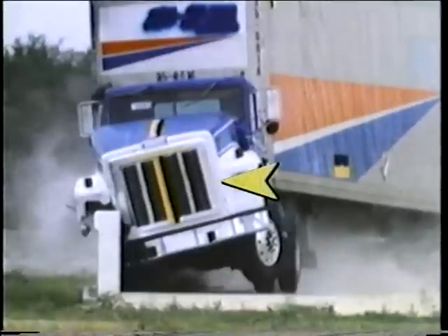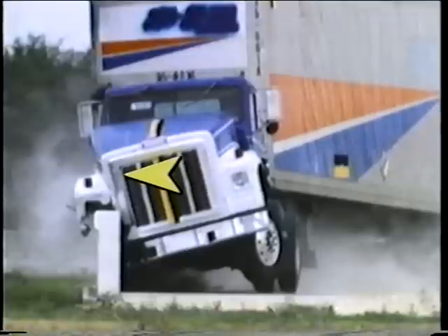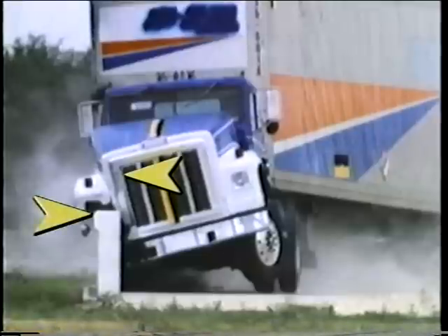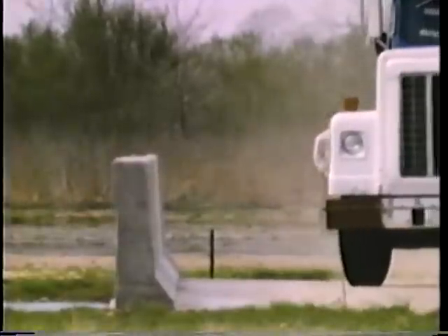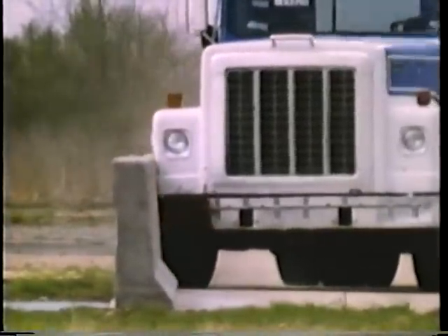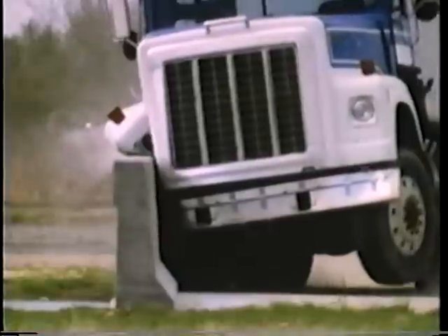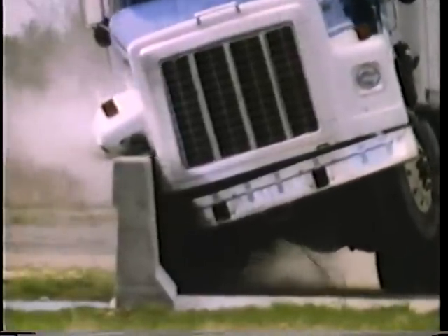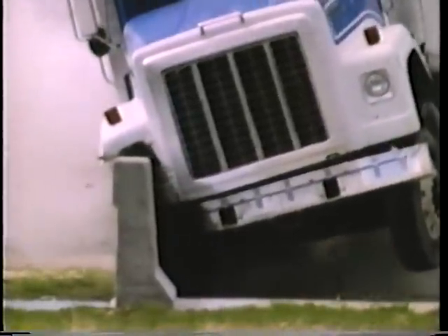If a bridge rail is too low, the truck will simply roll over on top of the barrier. When there's a good possibility that heavy trucks will strike a bridge rail, crash test experience has shown that the bridge rail should be at least 42 inches tall to provide an adequate force at the right height. The F-shape, New Jersey shape, and vertical wall can be used as PL3 bridge rails if their heights are increased to 42 inches and additional reinforcement is used.